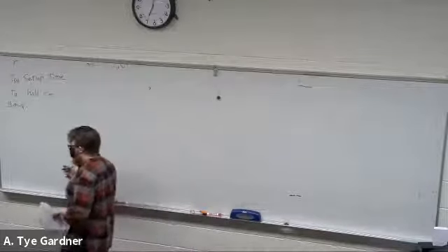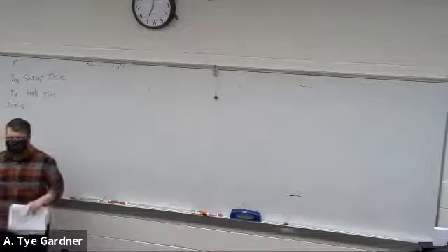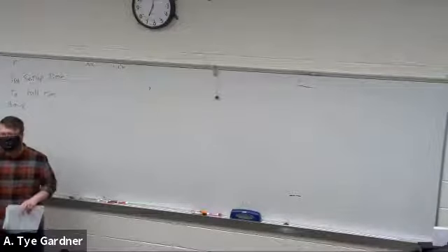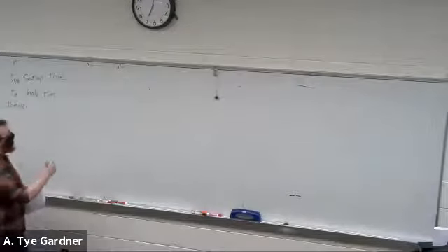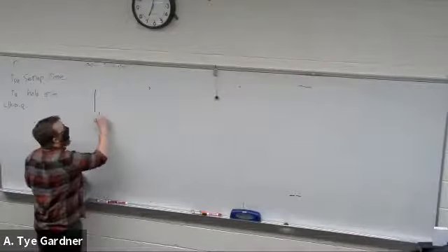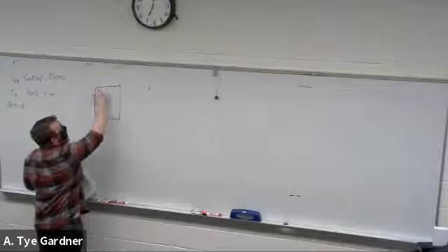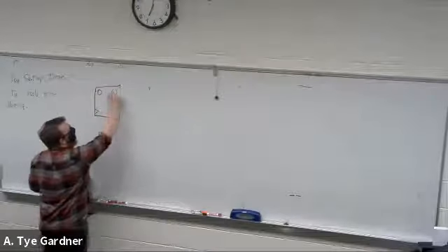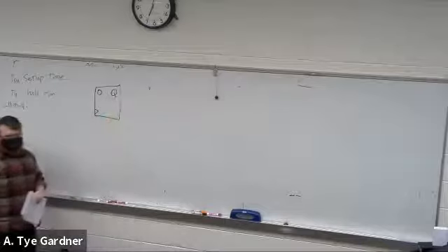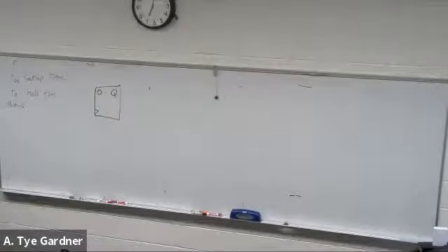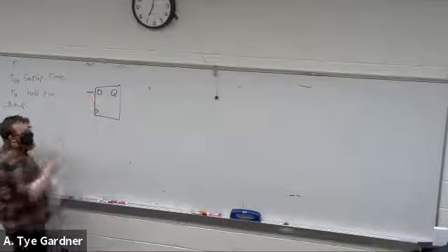Setup time is the amount of time required for data. We're going to do this all in the case of D flip-flops, like this. Super simple, super easy. A clock hits, we take whatever's on D and output it on Q, right? Setup time says that D must be stable.